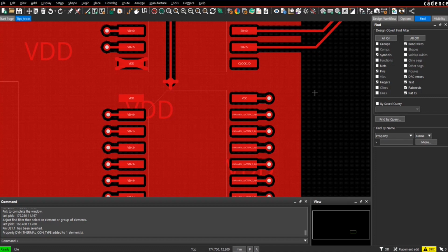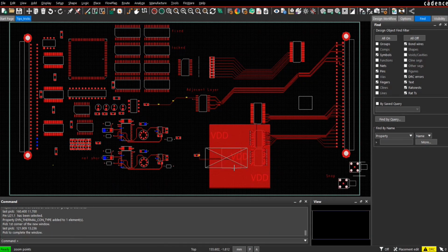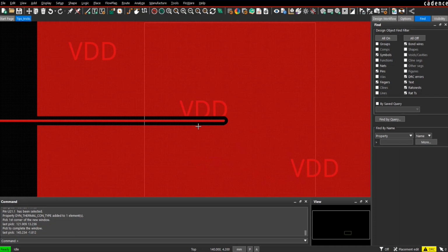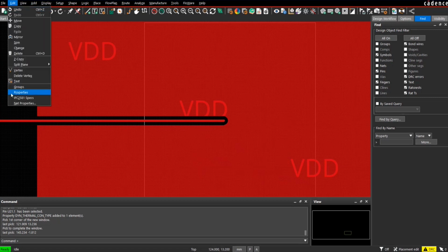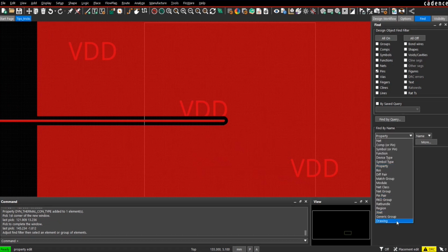Good. Let us talk about the possibilities to control the spacing between a C-line and the shape in a region. So I have here a region, and in this region, special rules are set up. So a smaller spacing between the C-line and the shape in the end. It should be 0.3 here in the default area, and here 0.1 millimeter in this constrained region. But you see, it's always the same here. And if you really want to have this solved in the right way as you want to have it, we have to set the property on the complete board drawing.